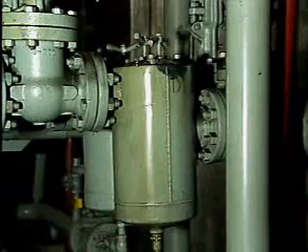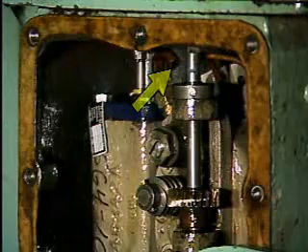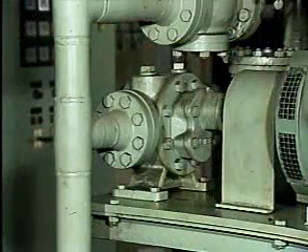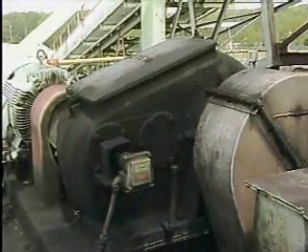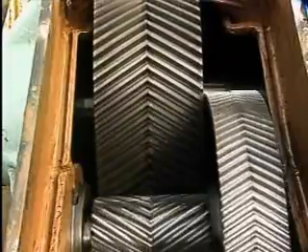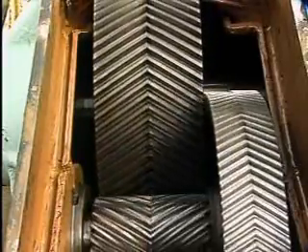Insufficient lubrication can be a result of clogged filters, clogged or improperly adjusted spray nozzles, or the improper operation of the lubricating system. Also, lubricant can be lost from a gearbox through a blown seal or a leaking joint. As you might guess, a problem that develops in a gear set's lubrication system may end up damaging the gears. Now, depending on the load in a particular gear set, this damage could occur almost immediately, or it could take some time to develop. One of the prime indications that a lubrication problem has occurred in a gear train is